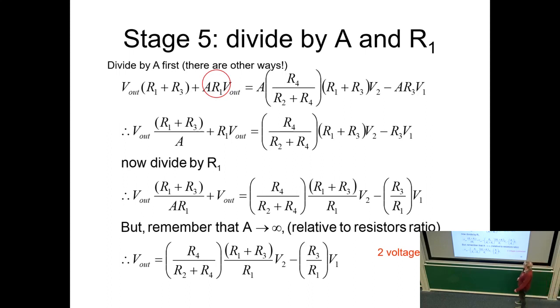Okay. So if we do that, this tends towards 0, we're left with V out. V out is equal to V2 minus V1, with a whole bunch of R's. Two voltages subtracted. We've made a subtractor. Scaling may be all over the place, but we'll solve these problems as we come to them. So what we'll do now is go, okay, is there a relationship between those values of resistance that we can work with to make life easier for us?